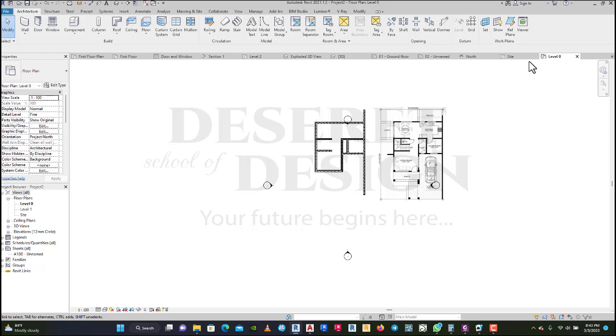Say you want to use a project you've done again, and that project you've done correctly. Anytime you want to do any project, whatever you brought in this project, you want the same thing. So that project you've done, you open it up, delete everything inside. Listen well. When the prompt comes to save, don't save. If you save, you will distort your actual project. So when you start deleting, when the prompt comes to save, don't save. Delete everything out of it.